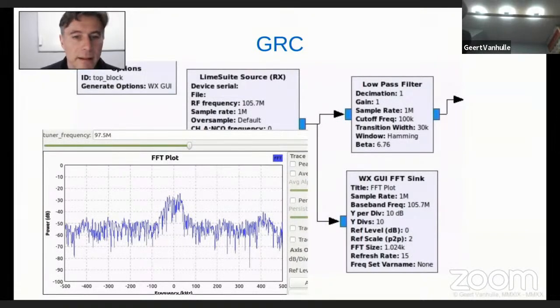And this 200 kilohertz of bandwidth is presented here as plus 100 kilohertz above the zero line and 100 kilohertz below the zero line. So our 0 hertz frequency line is actually the middle of our frequency of interest. You see, we have a down conversion to 0. Our baseband is below and above 0 hertz.